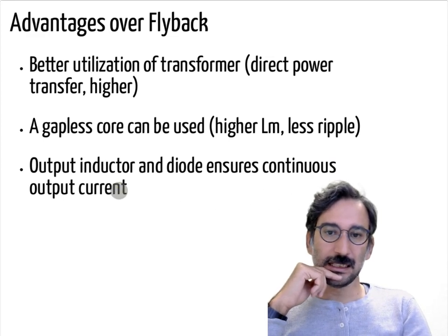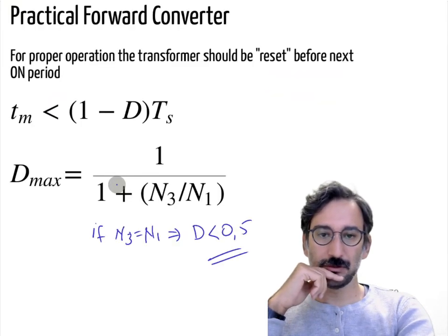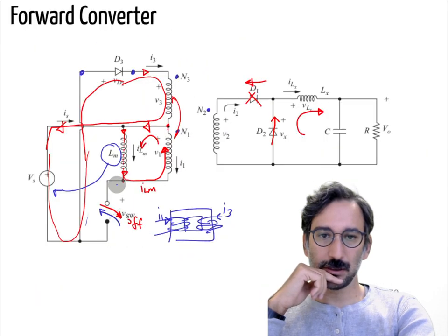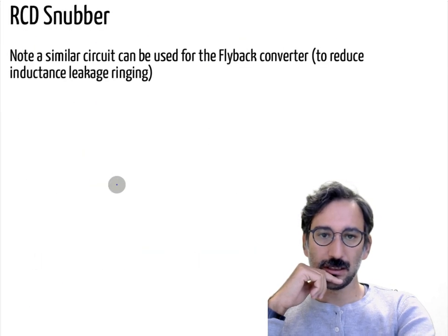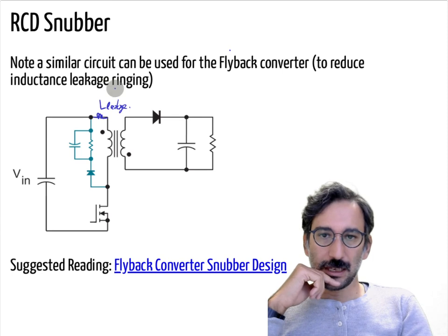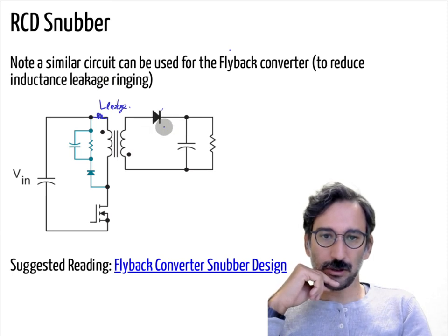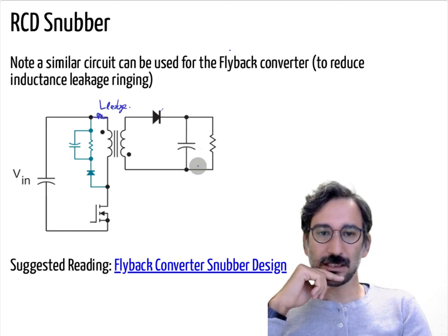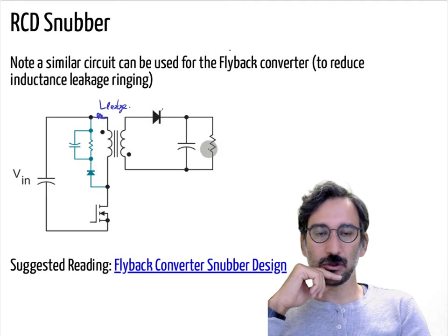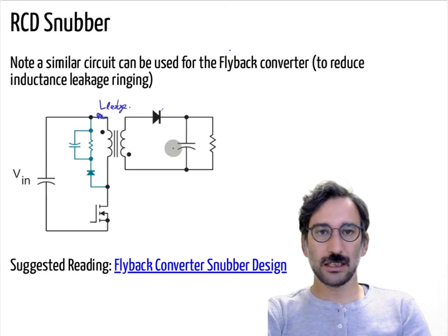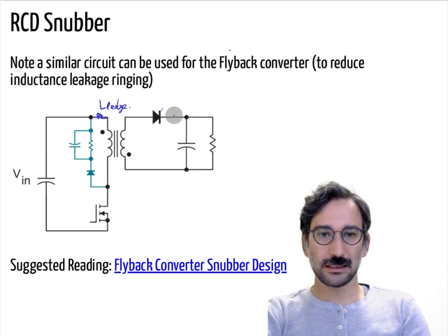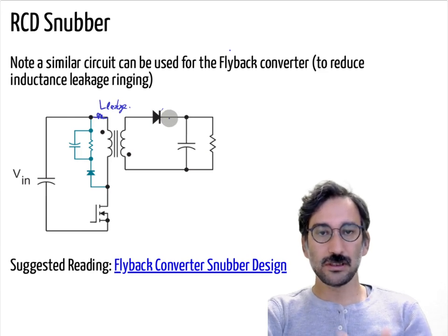And again, similar, let me open the flyback converter. In the flyback converter, that switch is turning on and off, and whenever it is off, you have just the capacitor to supply the output resistance, and you need to choose a large capacitor, because the current coming in from that side is discontinuous, it is on and off.